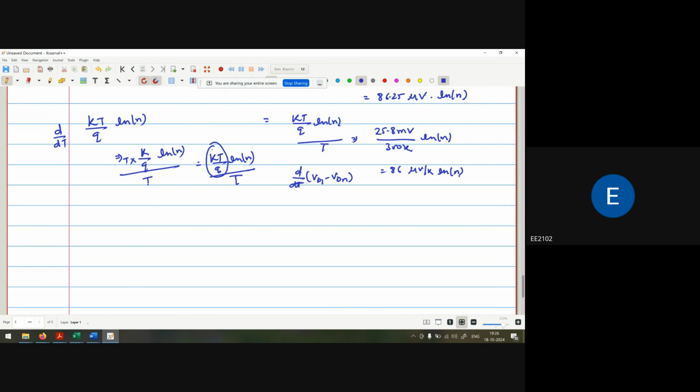Then if you go to the last part of this, you can see that we generally choose the value of n as 8. Why 8? Because this is the configuration of 8 diodes we are using. Now if I use a diode in this way, the temperature effect on this diode is very less.